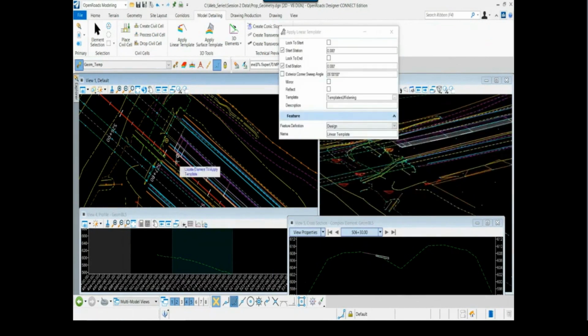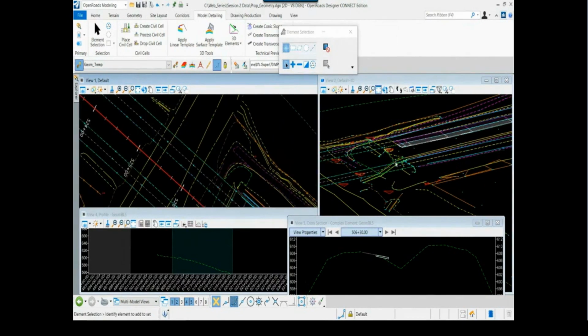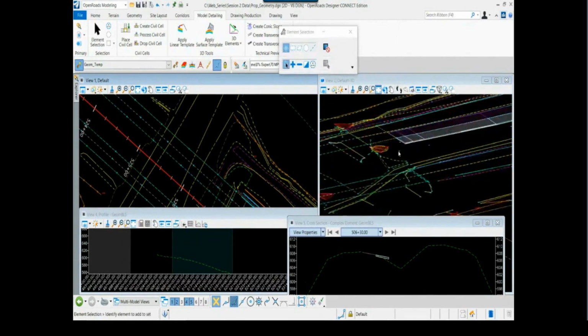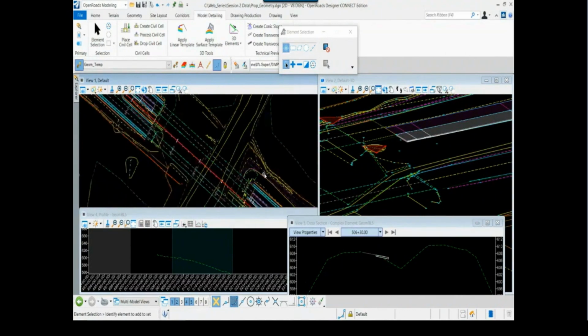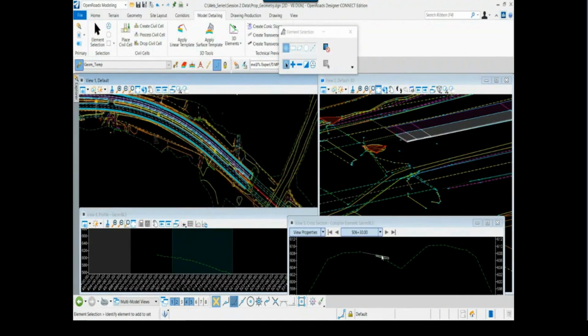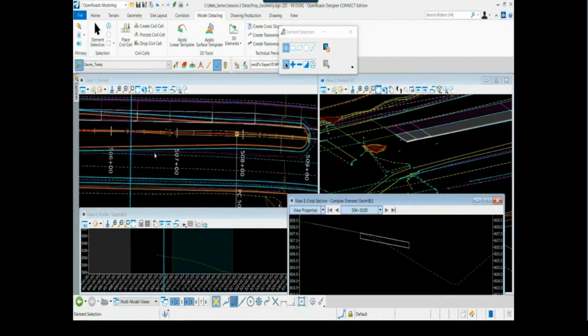We can even, well, we won't worry about the bridge at this point. I'll project it in a different way. But we now see that PGL based off the existing cross slope and widened. Now, I will point this out. In this case, for time's sake, we did not take into account, although we may do this at a later session in a SIG coming up, super elevation correction or milling and overlay. Again, our focus is geometry, so we didn't go through that process. We may pick that up at a later date in a separate maybe SIG session.